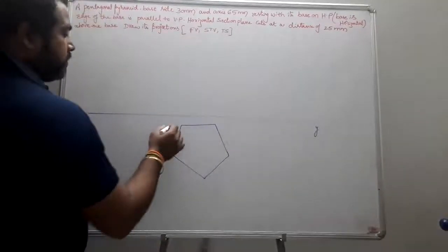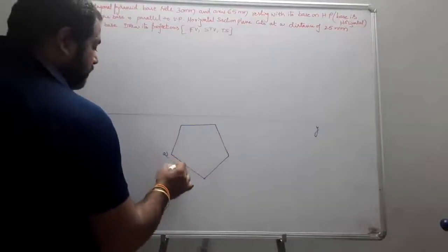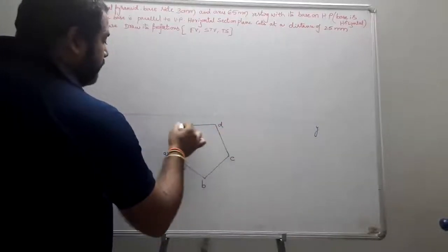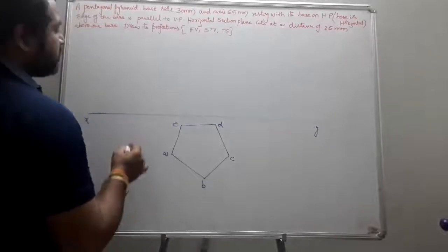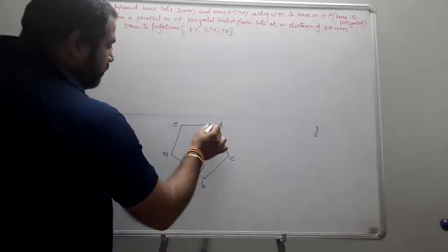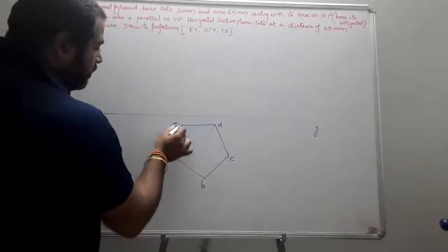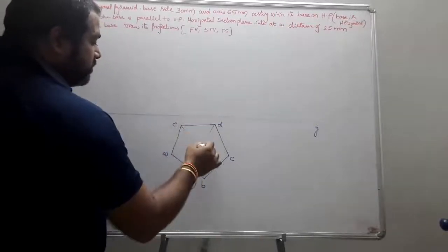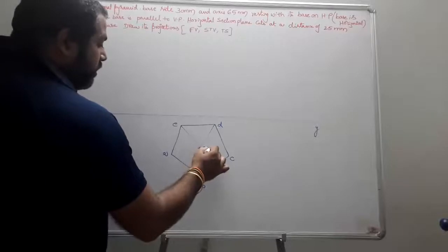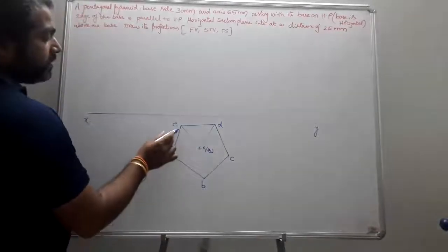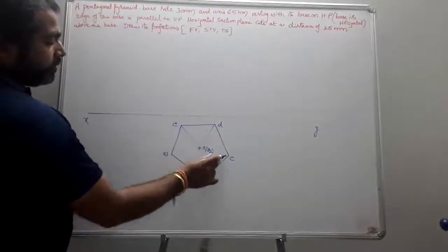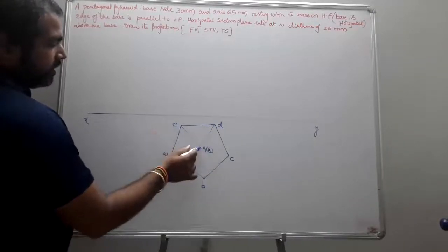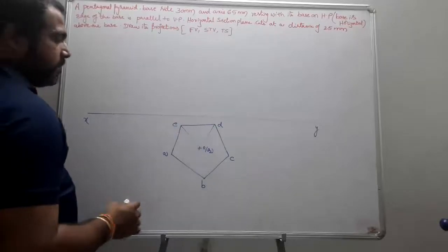Let us consider the points as A, B, C, D and E. This was a pyramid, so you are going to obtain only one set of points. Now put the axis, that is the origin. When you see the top, you are going to see the apex. How can you obtain your apex? Join one corner to the opposite side center, and another corner to its opposite side center. These two can meet at a common point, that is your apex point.